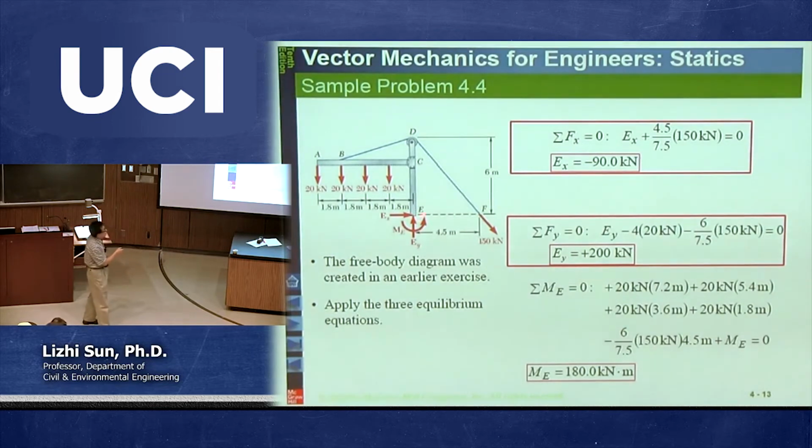And then what is the direction? In other words, clockwise or counterclockwise. You hold this point, and then this force acting on here has a potential to rotate this rigid body counterclockwise. If it is counterclockwise, you put the positive sign in front. Okay, so that's the contribution due to this force.